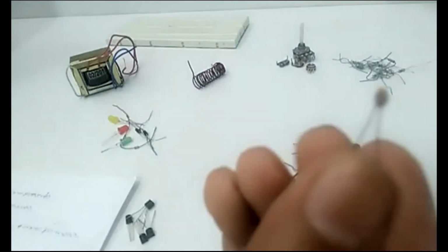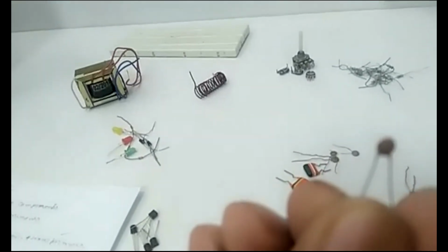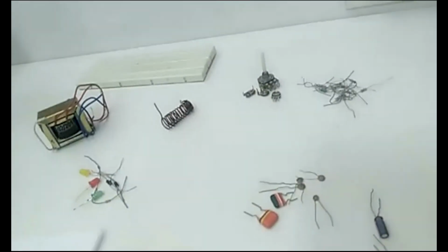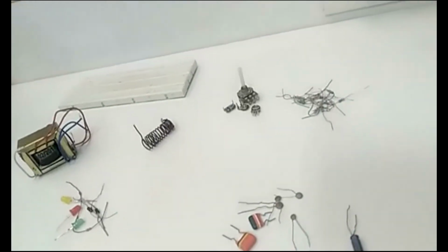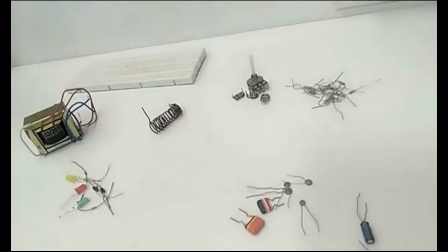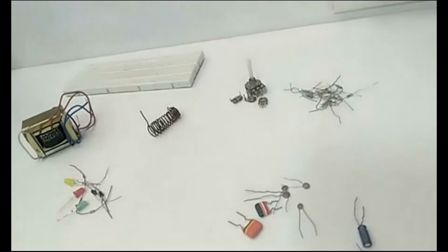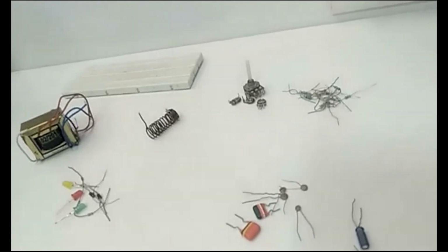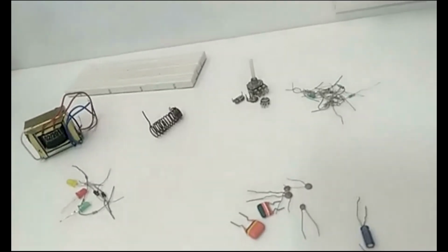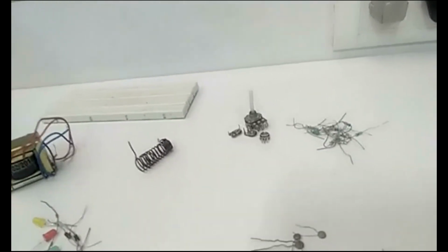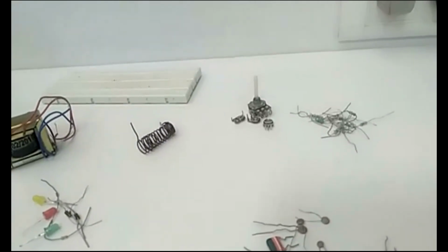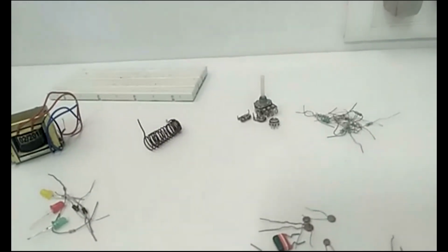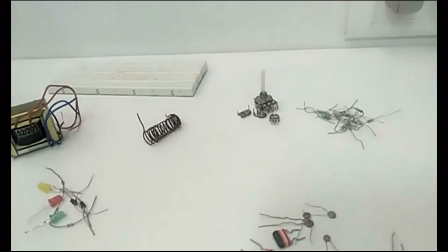In the case of a ceramic capacitor, the numbers are given in a form like, for this capacitance, 104. From the number you cannot say directly the capacitance value, so here also there is a code. The first two digits contribute directly, digits 1 and 0. Then the next one is similar to the color code of a resistor, it is the multiplier. So 10 power 4, in picofarad.